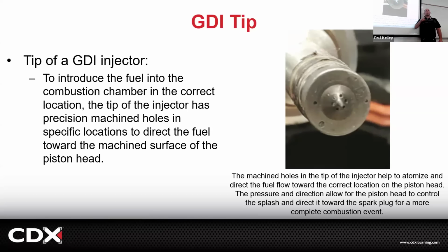This is the problem. What if you do one injector and the one injector is really clean and the other 3 are kind of dirty? Now there's an imbalance. So we brought in a whole other set of DTCs now that are a fuel cylinder to cylinder imbalance. So if you have a brand new direct injector and 3 old direct injectors, you may get a cylinder imbalance, which you've got to fix. How are you going to fix that? Probably going to replace the other 3. Yeah, so if you go into service information and it says if you're replacing one injector, replace all, that's your justification for doing so.